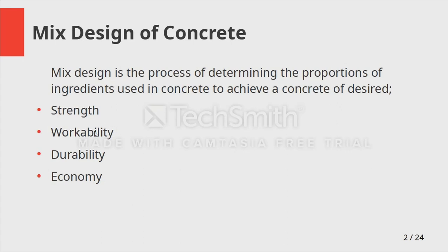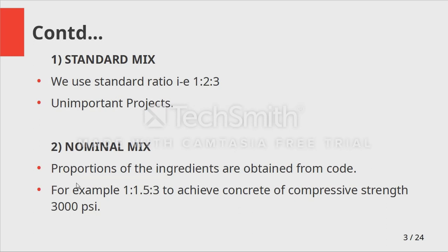Similarly, workability basically tells you how easily you can handle a concrete on a site. In terms of slump, you measure the workability. And durability means that when you make a concrete, during its design period, it should not deteriorate. So to achieve such kind of concrete we need the mix design. Similarly, economy, that your concrete shouldn't be so expensive, but it should be as cheap as possible. So to achieve such kind of mix or concrete, we need to study the mix design.